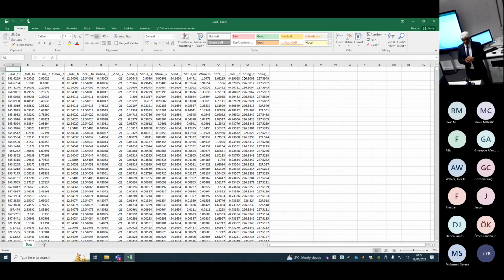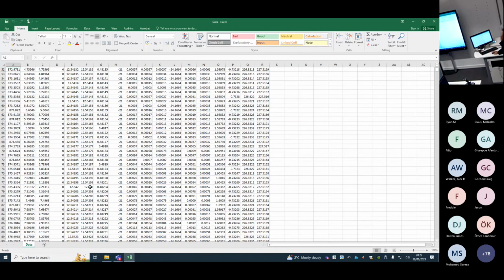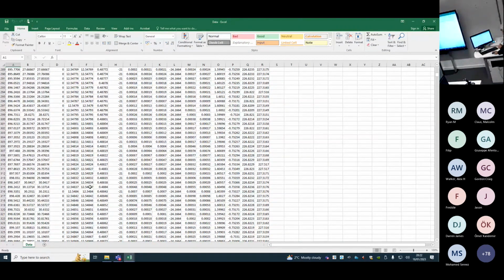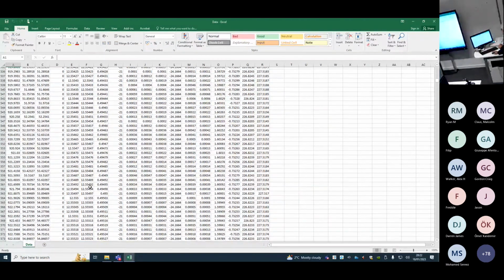But now you're going to ask me, I also at some stage wanted lift and drag coefficients. Where have they disappeared? So what happens is every time you add more variables, the file will grow. So if you scroll down to the bottom of the file, wherever I've made changes to the output, you will see a new header.